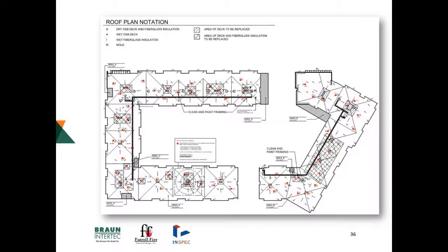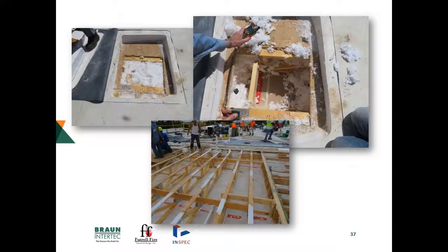And it wasn't a ton of work done in the center of the roof. So that was kind of our whole concern: what if we start getting into this and we really should have torn the entire deck off? But we knew enough about what repairs had been done before to reasonably figure out that we could go after this through the perimeter. And it did turn out that that was good, and there wasn't a lot of deck replacement required on the project. Here's a couple of photos at the top showing those test cuts that were done. And I forgot to say, I think there were 60 test cuts done a month prior to construction.